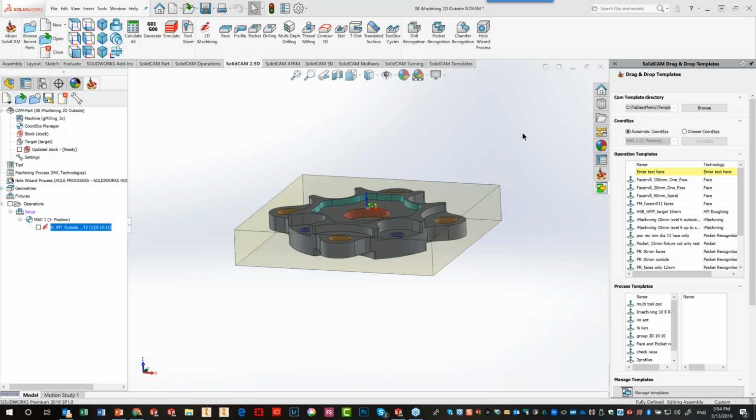It's just for you to see. So you would have to re-click on the part to update the actual model of the stock. Remember, that's just a model. It's not the real stock. It's just for you to visualize it a lot better. Right, but to Harry's point, if we were to shift the x-axis 45 degrees around Z and then come back in and rebuild that stock.